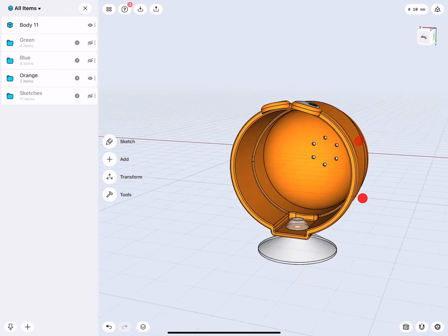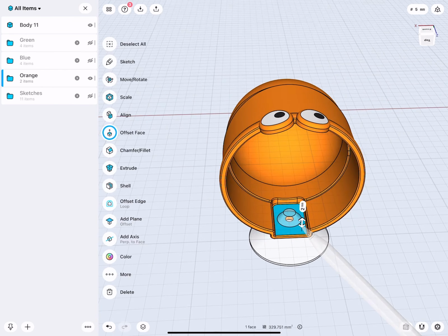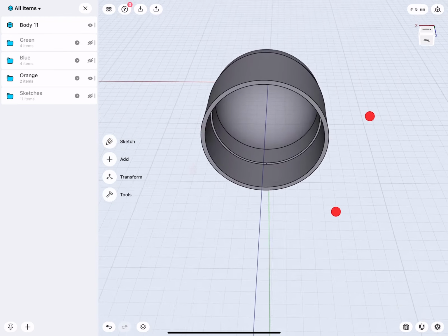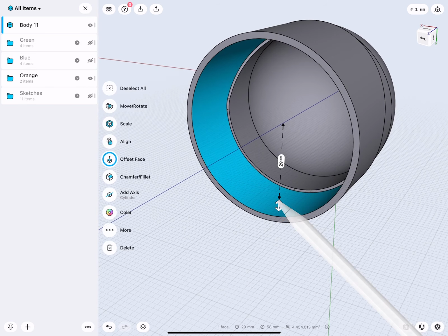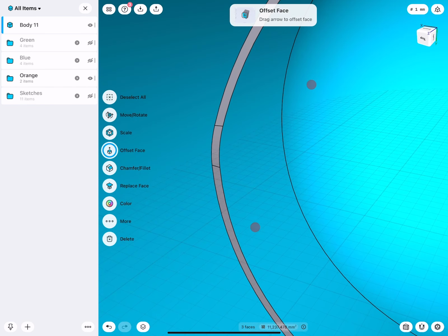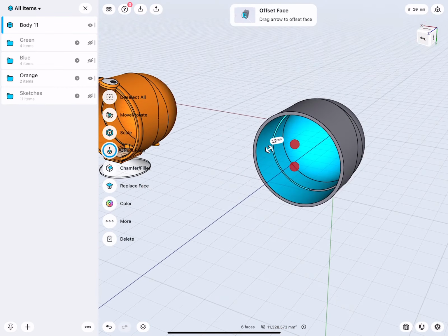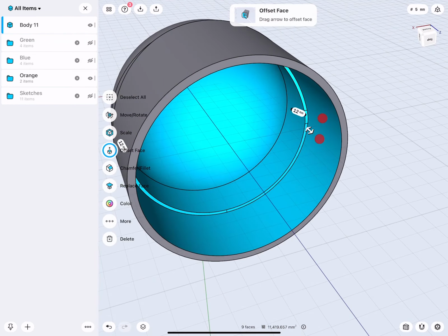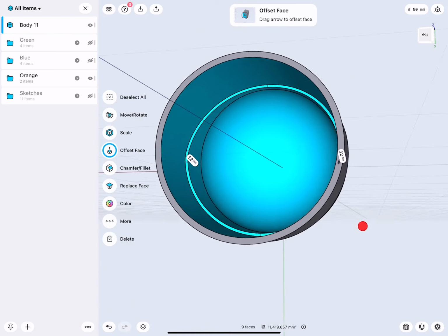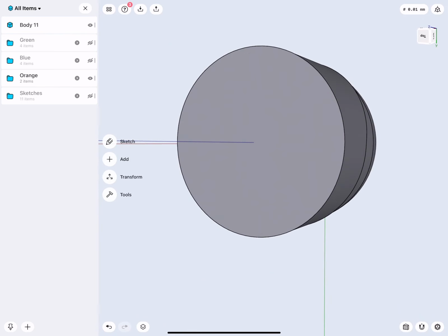When we go back to our orange one, however, we also see here is this area that's carved out. So when I go back to here, then how do I now remove the opening, patch the surfaces in, and this is way too complicated. So welcome to direct modeling. Now we can always undo commands by selecting all the faces the shell command created and simply delete them. And we're back to this one. Really nice.